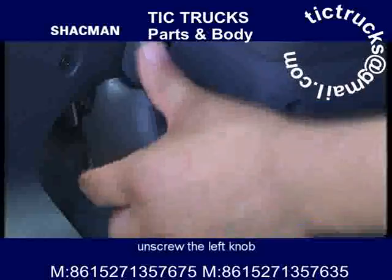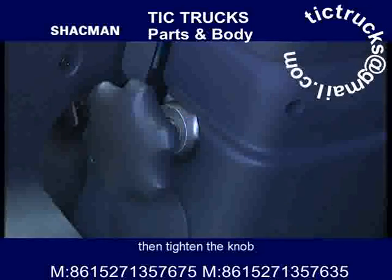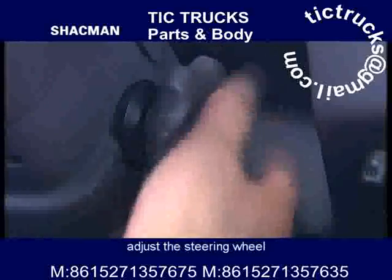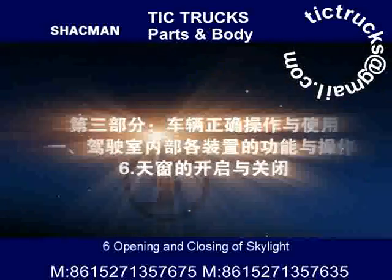Adjustment of height. Unscrew the left knob. Adjust the steering wheel to the desired height. Then tighten the knob. Adjustment of angle. Unscrew the right knob. Adjust the steering wheel until the desired angle is obtained. Then tighten the knob.